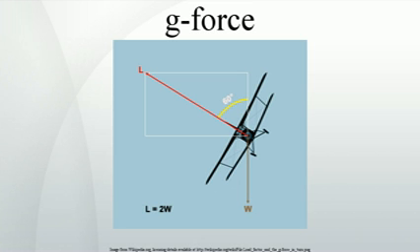In the case of an increase in speed from 0 to v with constant acceleration within a distance of s, this acceleration is v²/2s. Preparing an object for g-tolerance, not getting damaged when subjected to a high g-force, is called g-hardening. This may apply to, for example, instruments in a projectile shot by a gun.